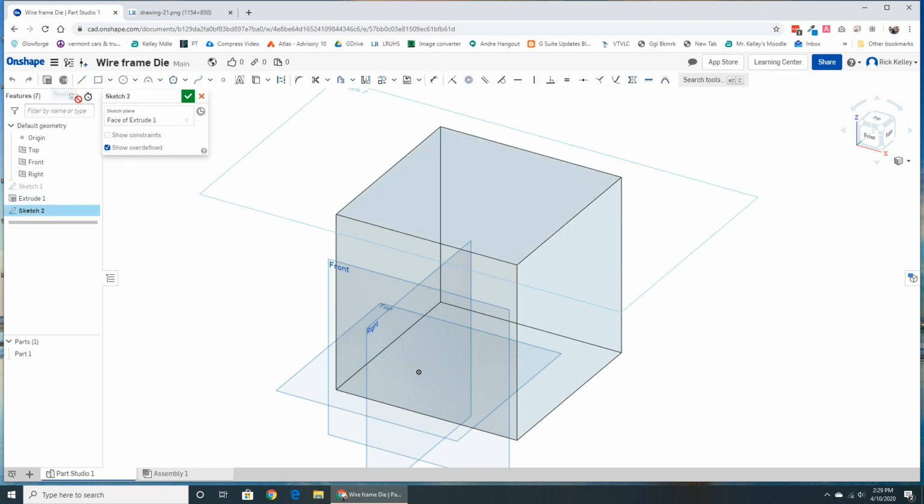Sketch. And now I'm going to grab the circle tool, and let's just put a circle in here. We'll make this the one circle side, and it wants to know the diameter of that circle. Radius is 0.5, so my diameter is 1. And now I have my circle. Next thing I need to do is tell the software where the circle is. It knows how big it is, but notice it's blue while everything else is black. Blue means you haven't fully defined where something is or how large something is. Black means it's fully defined.